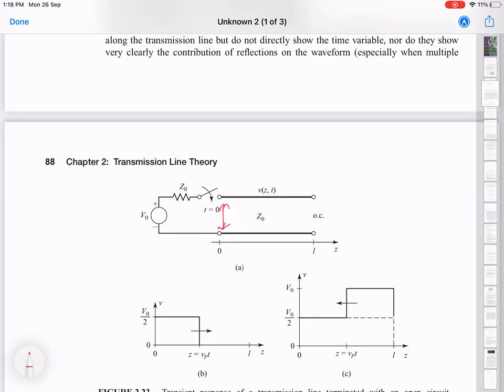Okay. So one last thing to think about. If I have a transmission line of Z0, and then I connect it to two transmission lines like this, they are actually connected in parallel. So there's an incoming line, and then there are two lines which are going away from it, and they are both Z0.